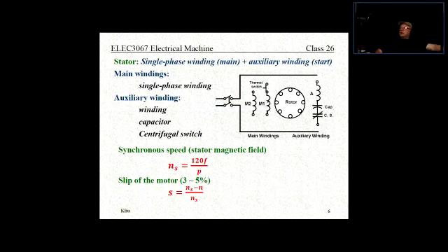And if you use just one, you're not going to use as much power. All right. So if you use just one, you're supposed to use the one with the thermal switch. Because if you use just one and you connect the second main winding that is not connected to the thermal switch, you are putting yourself in a dangerous situation where you can burn out the coils if the motor overheats. Of course, that switch is going to open, but that winding is not connected to it. It's just this one that is connected, right? So if you use a single one, use the one with the thermal switch.